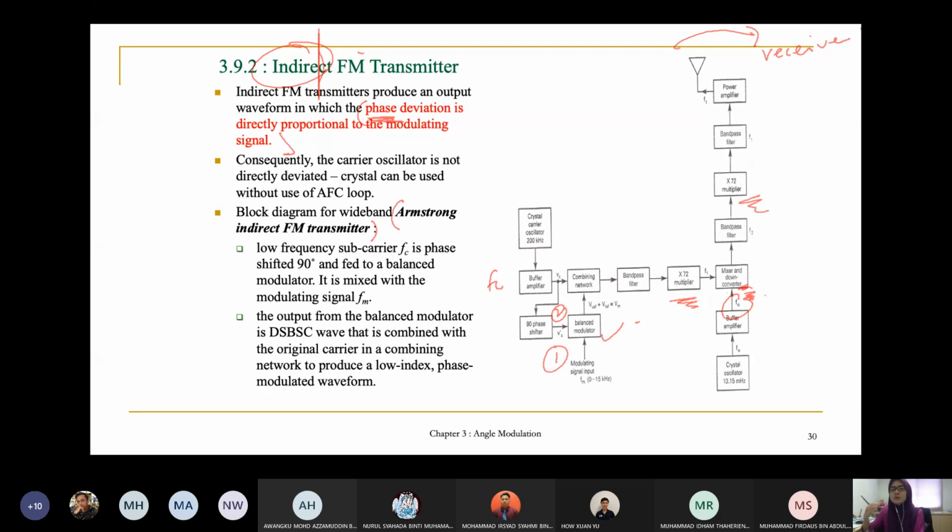Okay, so from this figure, you can actually see the importance. Why do we need to know the heterodyne process and the multiplication process that we have learned in the previous slide? Because you should know which parameters are affected. For example, at the output of the multiplier, you must make sure that the parameters Fc, delta F, and also the modulation index are multiplied by 72.